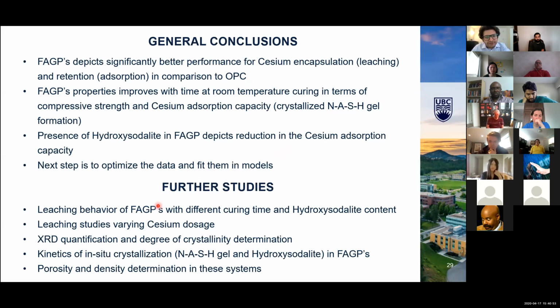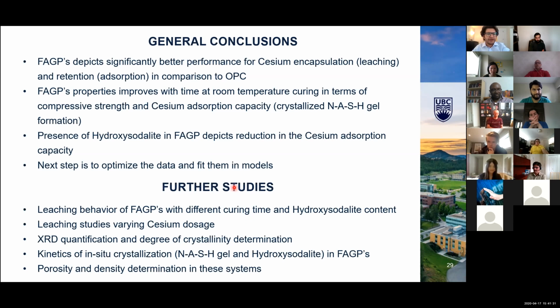So apart from this, the further studies that I'm planning to do is to study the leaching behavior of fly ash geopolymer with different curing times. I conducted the test for 6 months for the geopolymers cured for 6 months, but I want to see how the microstructure change with different curing times is affecting the cesium encapsulation, and also varying the hydroxysodalite contained within the material. Also, leaching studies varying cesium doses is also my plan of work. That's what I'm aiming to do as well.